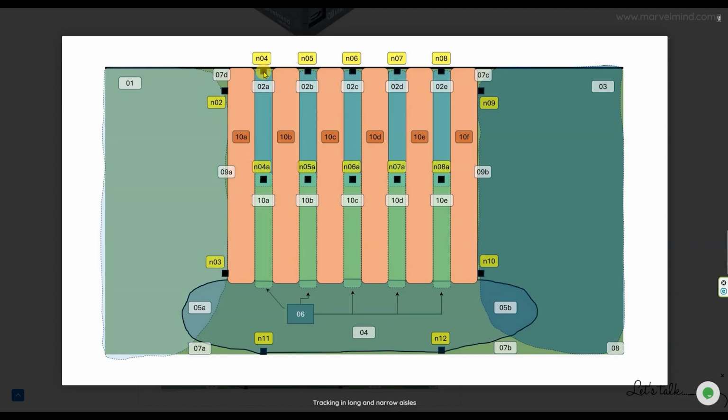So what do you do? Well, the simplest solution: you install one beacon here as before, and another beacon here, maybe around 25 meters. And the length of the submap would be 30 meters, with this area being a handover zone between submap 02A and 10A. And this is the handover zone between them. So this beacon starts effectively showing from this area.